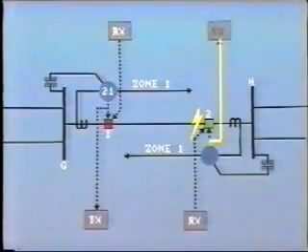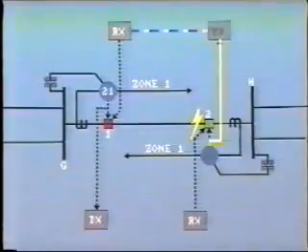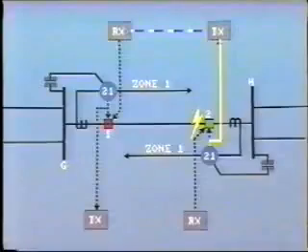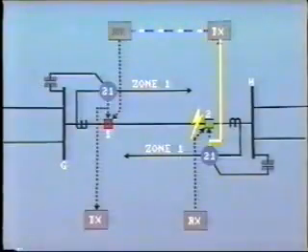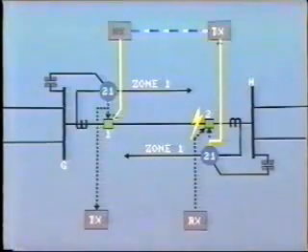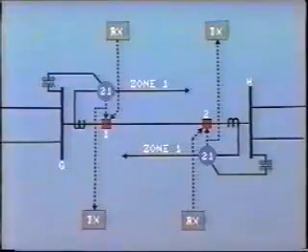At the same time, it immediately switches the transmitter from guard to trip frequency. This new frequency is sent along the communication channel. At station G, the receiver picks up the signal and immediately trips breaker 1. So this arrangement achieves the objective of high-speed tripping at both ends, and at the same time it prevents overreach and false tripping for external faults.